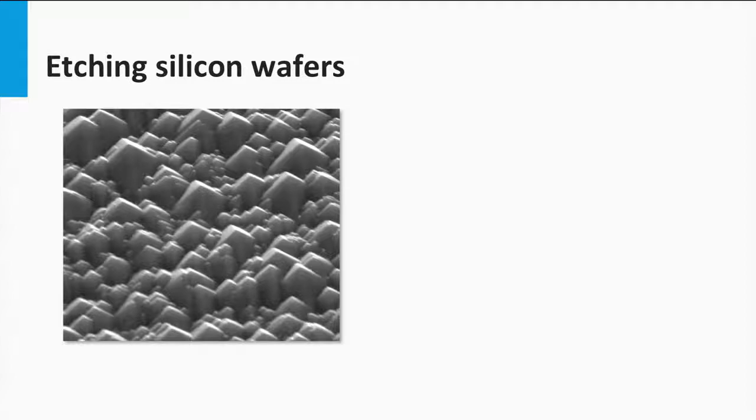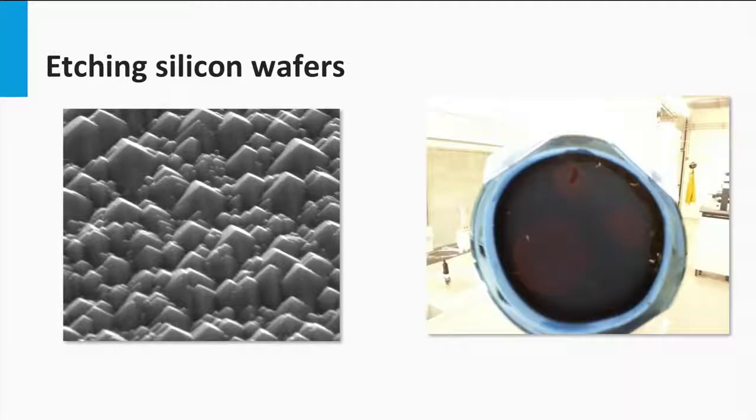The texture on the wafers can be realized with wet etching approaches. Here you can use an interesting property of the 100 surface. This anisotropic etching can be used when etching a crystalline silicon wafer with an initial 100 surface orientation. Etching of such a wafer leads to textured surfaces with a pyramid structure having only 111 oriented surfaces. In this picture you can see such a textured surface of a monocrystalline silicon wafer as processed at the Else lab in Delft. Using such etching procedures, it is even possible to have a silicon wafer looking black, as shown here in the second picture.